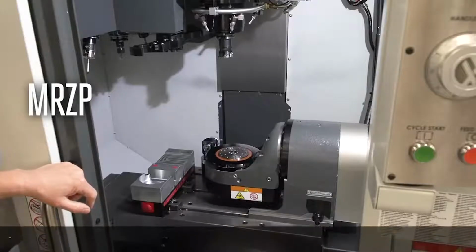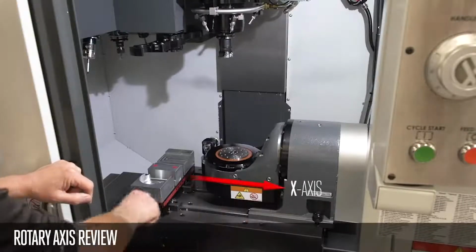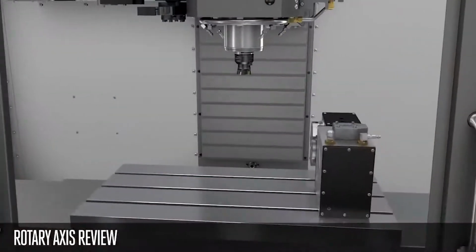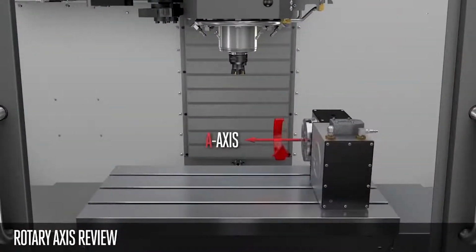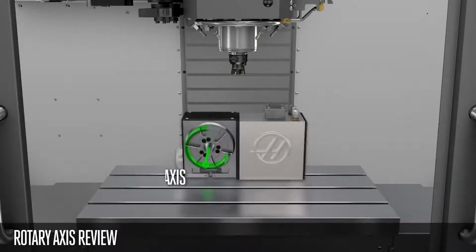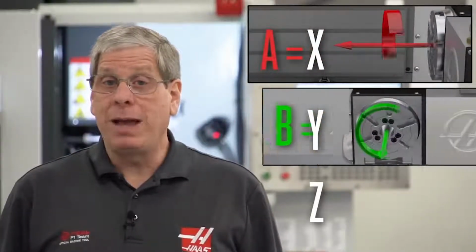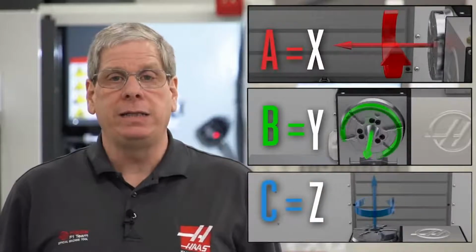The mill's three linear axes move like this: X, Y, and Z. A rotary axis mounted here will rotate about the X-axis. This is an A-axis. A rotary mounted here rotates about the Y-axis, so this is a B-axis. And a rotary mounted here will rotate about the Z-axis. This is a C-axis. Get it? X, Y, Z, A, B, C. A about X, B about Y, and C about Z.